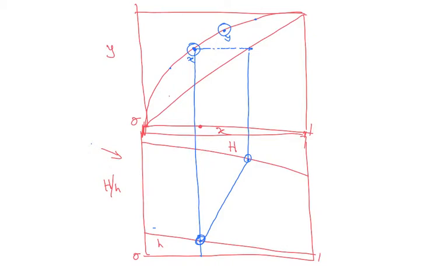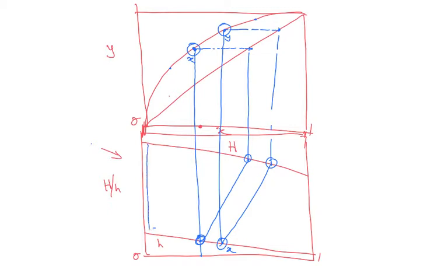On the x-axis, you just project it down, so you get your x, but then for the y, you draw it across and then drop it off to the capital H. If you keep drawing this, you will see that the tie line is kind of vertical over here on the left hand side, and it will start taking some slopes, but then it will also become vertical over here.